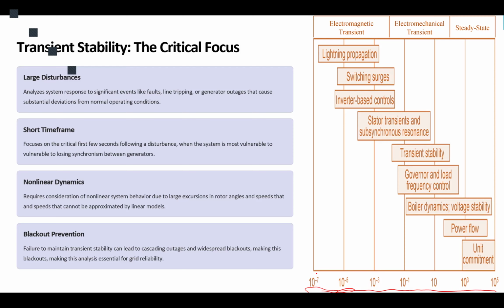When you want to calculate the RMS, you calculate it based on all the data you have in at least one cycle of sine or cosine, correct? Again, impedance depends on frequency. That reactance is either j omega L or 1 over j omega C. We have omega in it. So meaning we have a frequency, meaning we have to have at least one cycle of sinusoid happen so we could have the frequency or the averaging RMS.